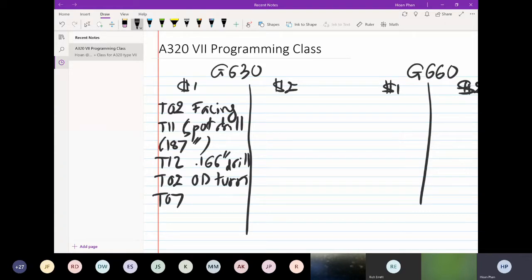And in this case, if you can calculate it, and then you can see the milling section right there, the width is only about 150 something. So right here, we can use a 1/4 inch end mill. It should be okay. And we can use square end mill.